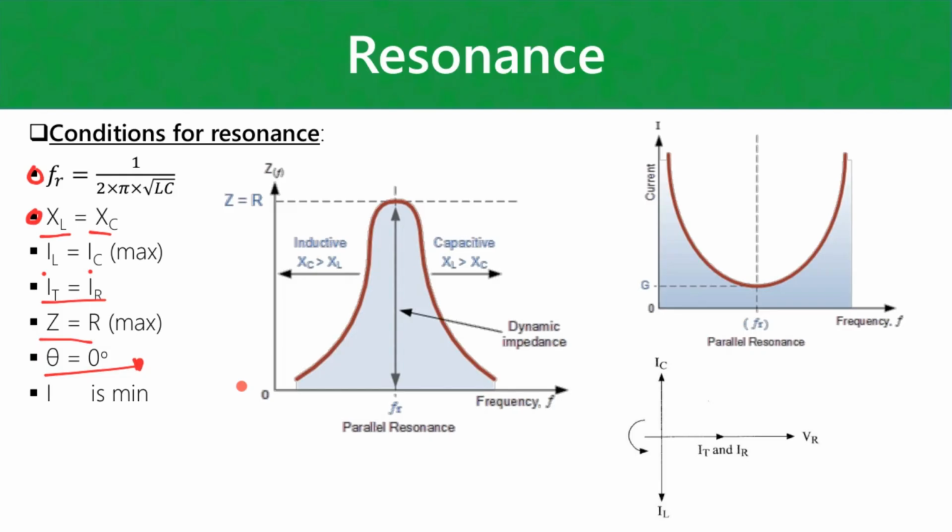And yeah, so there are your curves. So first up that we have here is the impedance. As the frequency is increased from 0 towards the resonant frequency, before you reach the resonant frequency, your circuit is going to act like an inductive circuit, and then increasing the frequency past the resonant frequency is going to force your circuit to act as a capacitor or RC circuit.